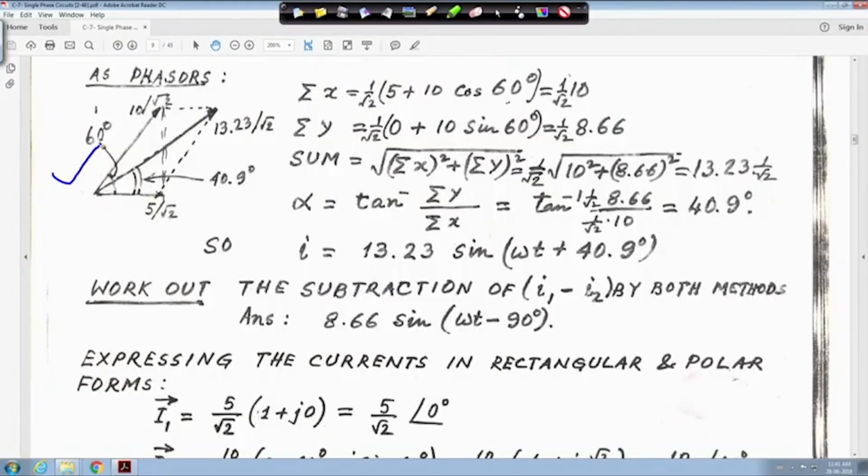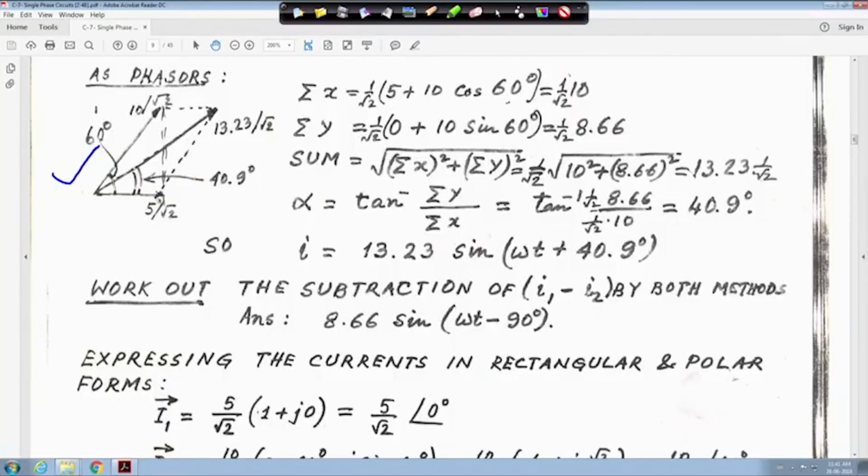Okay. So, we are back again. I hope you have understood this. Whenever you draw a phasor diagram, it should be an RMS value, keep it in your mind, do not take your peak value. And the way I told leading, lagging, a little bit of understanding is required in AC circuits. When you have understood this, everything will find too easy, right.